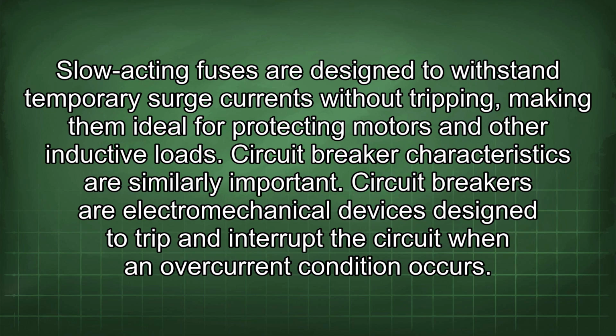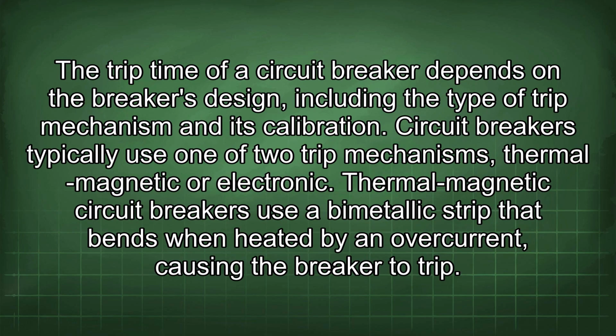Circuit breaker characteristics are similarly important. Circuit breakers are electromechanical devices designed to trip and interrupt the circuit when an overcurrent condition occurs. The trip time of a circuit breaker depends on the breaker's design, including the type of trip mechanism and its calibration. Circuit breakers typically use one of two trip mechanisms, thermomagnetic or electronic.